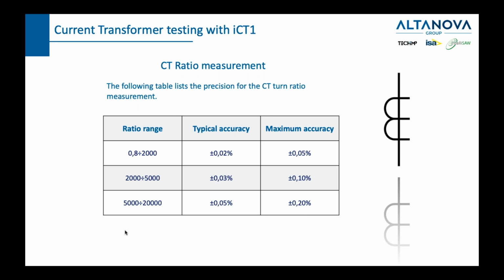Actually, if I haven't mentioned it, how we do a test, what we actually do, we generate on the secondary side the voltage, high voltage, and we measure on the primary side. If you have a 1000 to 1 CT, and if we generate, let's say, 1000 volts, which we don't, we usually generate much less, but let's say, just for the sake, 1000 volts on the secondary side, we will be measuring 1 volt on the primary side. And you need to measure that with the accuracy of 0.025, for example. So this is really, really accurate device.